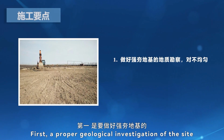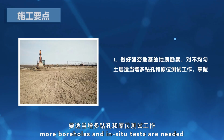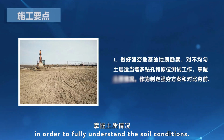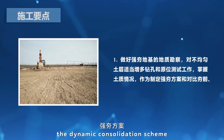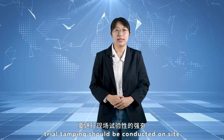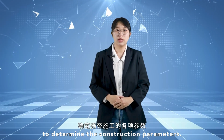First, a proper geological investigation of the site must be carried out. For non-uniform soil layers, more boreholes and in situ tests are needed in order to fully understand the soil conditions. This serves as the basis for preparing the dynamic consolidation scheme and for comparing the reinforcement effects before and after tamping. When necessary, trial tamping should be conducted on-site to determine the construction parameters.